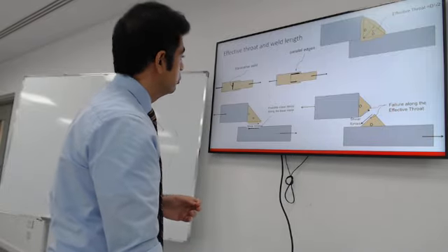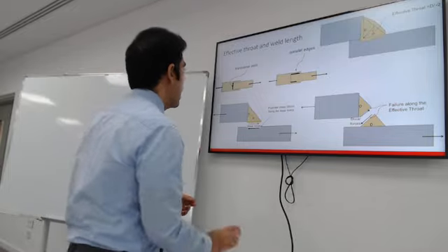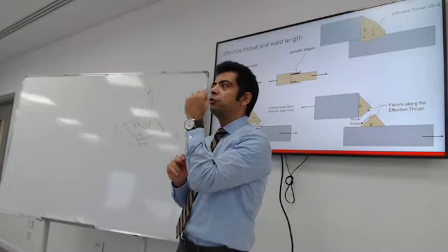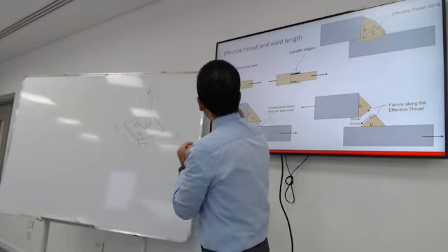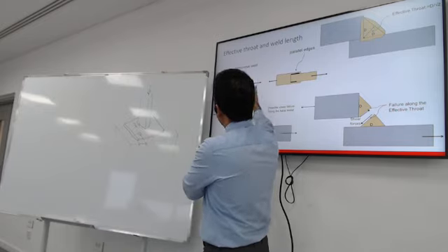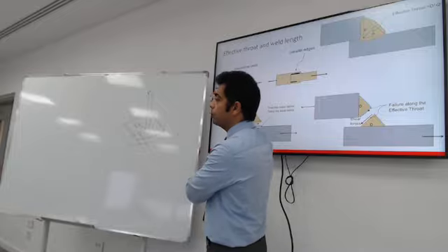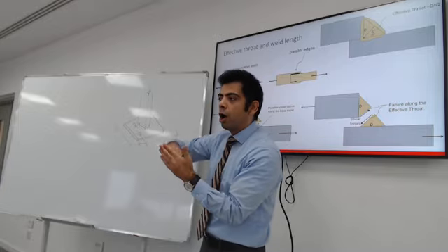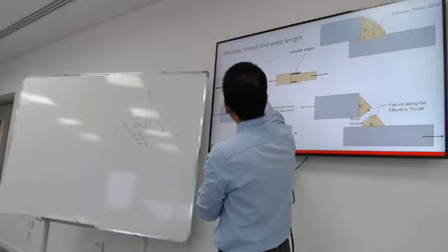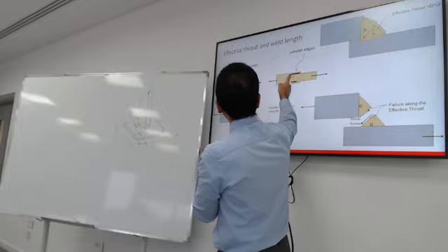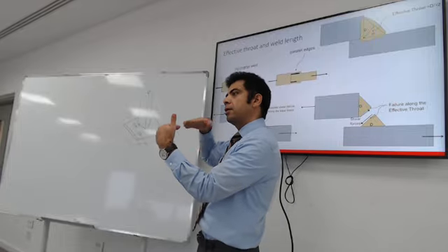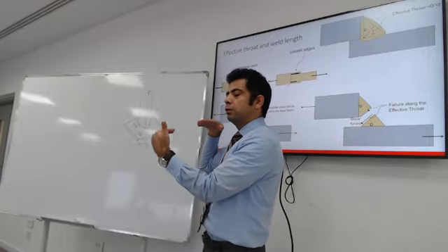I wanted to show you how the forces on your weld can be in two different directions. If there is tension in this plate, it's causing force perpendicular or transverse to the longitudinal direction of the weld. In a similar connection, but where you're welding on the opposite sides, this force is parallel to the longitudinal direction of the weld.